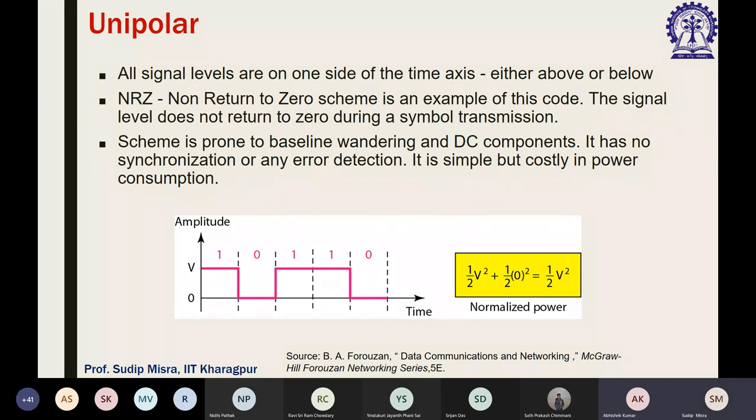Due to this, the spectrum creates very low frequencies. This comes from Fourier analysis, which you don't need to think about too deeply, but just remember that the spectrum is going to create very low frequencies due to constant voltage levels for long durations of time. These frequencies center around zero frequency, and are called the DC component, the direct current component.